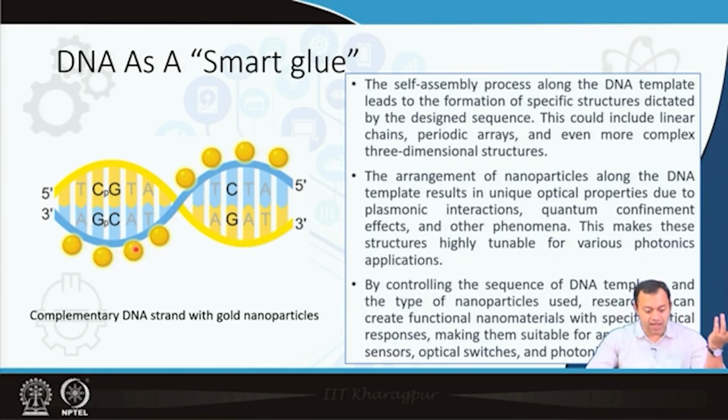And when you have the same electron cloud combining together, they will talk and they will resonate, and the output result is creation of a huge LSPR signal, localized surface plasmon resonance signal, that could be utilized as a sensor, because these signals that are generated by the free electrons present in these gold nanoparticles are very, very susceptible to any change in the local refractive index.